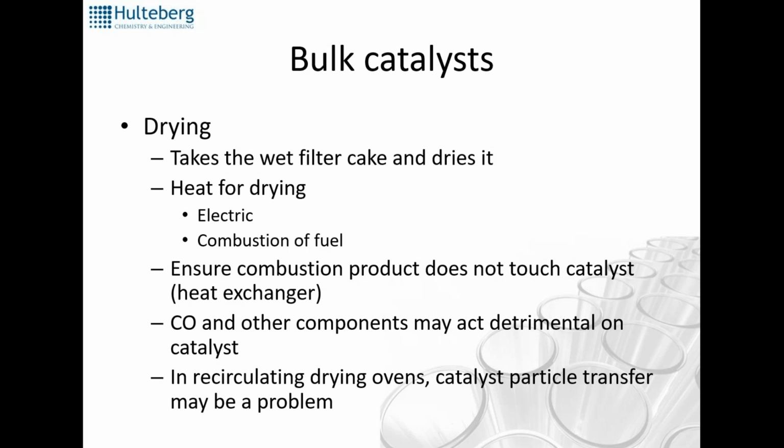Say, for instance, that you want to do selective hydrogenation with a silica based catalyst, and mixing it with some alumina, which has acidic sites, might change your selectivity, so that you get problems with dehydration instead of hydrogenation, or losing selectivity basically by having material carryover from one batch to another.